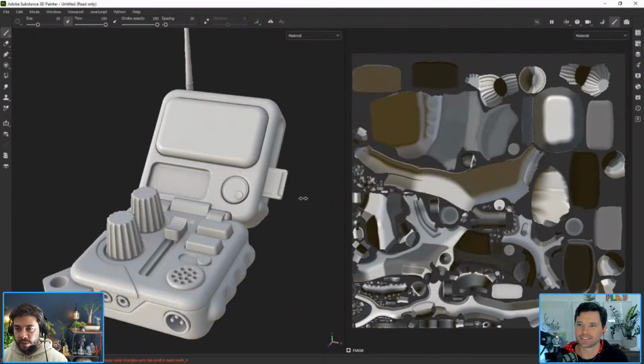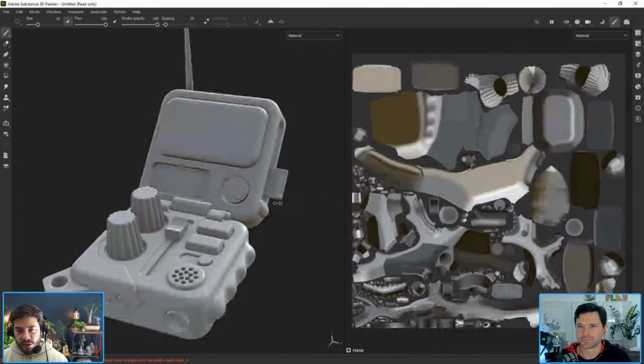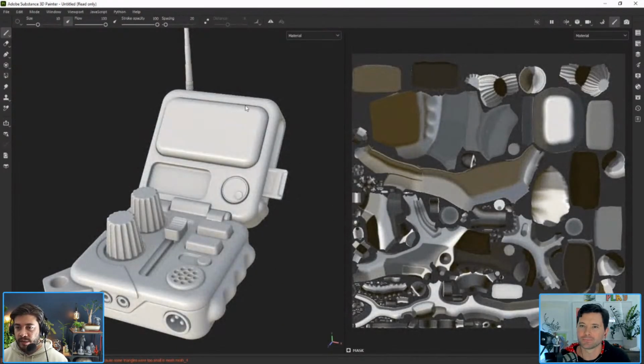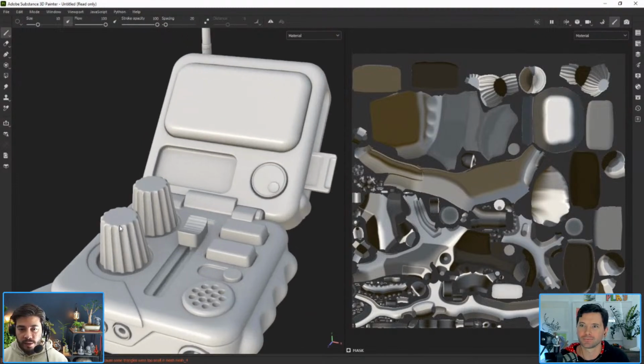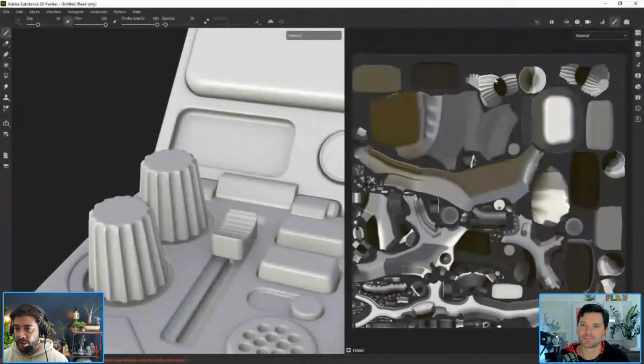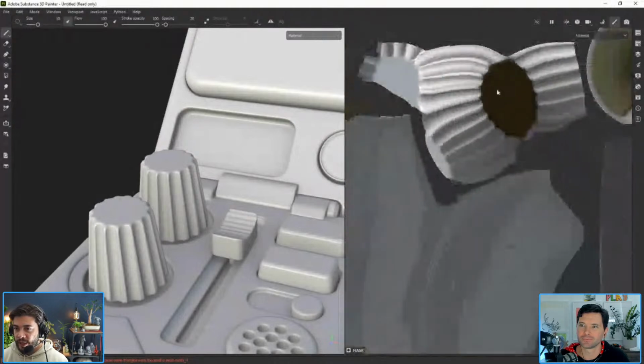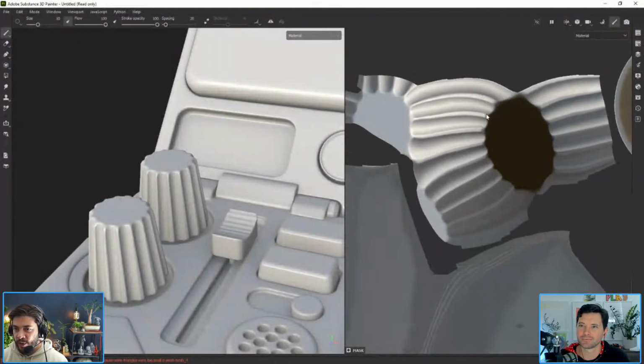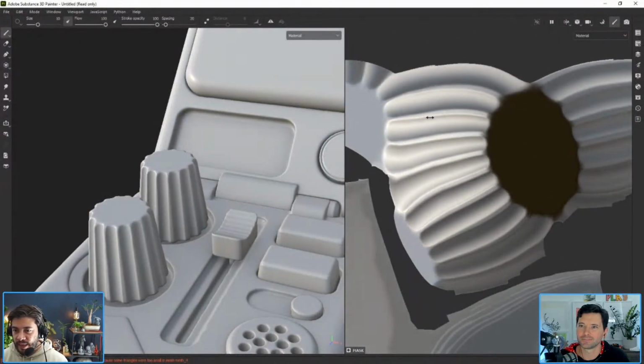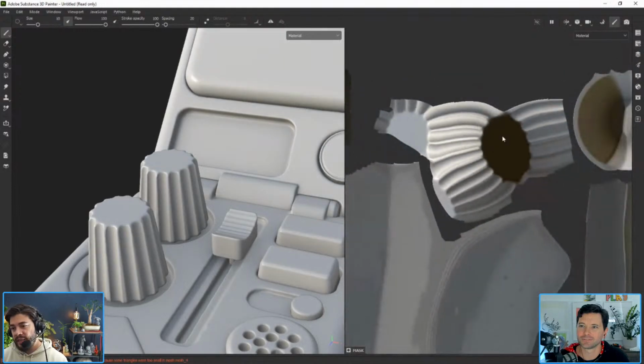You see that as I move the light, holding shift and right click, it reacts the same way in 2D as in 3D. So for example, these little dials here, those are probably these things here. It's not the greatest thing, but it will work. So you see, it has the same effect. It's just that these UV islands, these little sections here, is what the software uses to know how to wrap a texture around it.